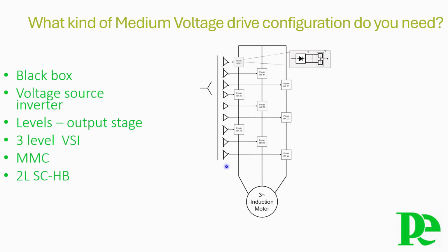The integral dry multi-winding transformer provides adaptability to available input voltage, and clean input power thanks to the cancellation of the harmonics by the phase displacement in the secondaries. Multi-pulse inputs go from 18 to 54. It also provides isolation from the grid, avoiding potential resonances and reducing impact from utility transients such as lightning and other equipment switching.